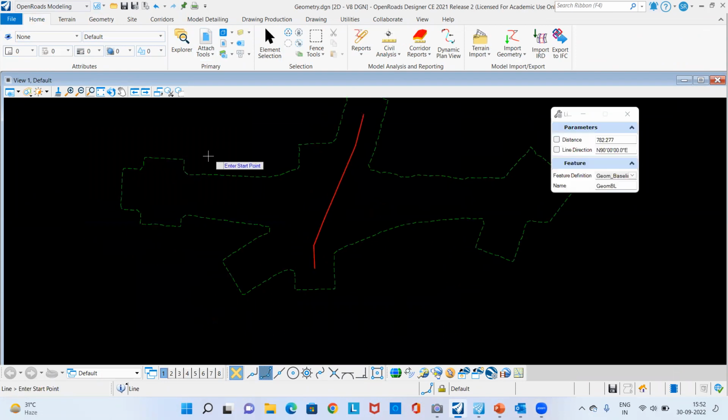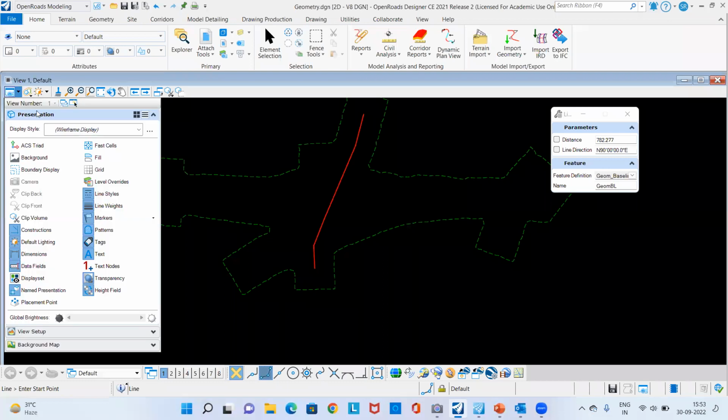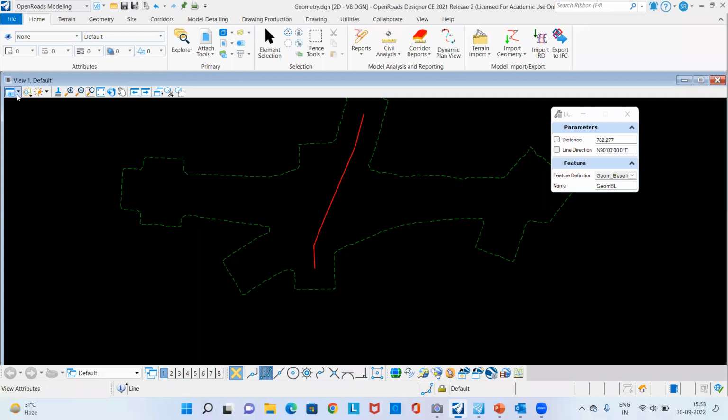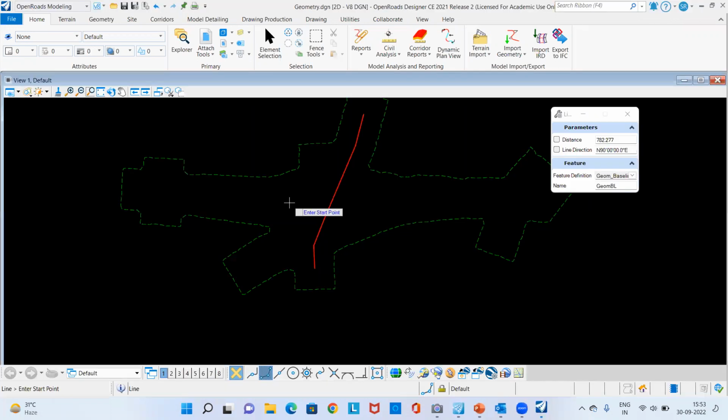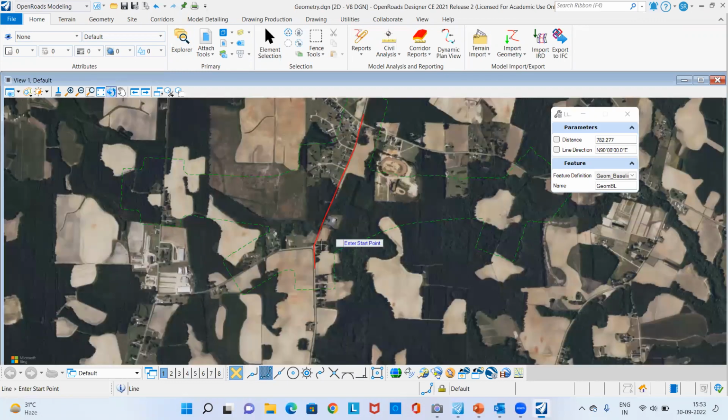Okay. Now let's check our integrated map. So the GCS is set. To view the integrated map, you must set the geographic coordinate system. Only then can you see this option here. You have three types of maps here: street map, aerial map, and hybrid map, a hybrid of both. Let's see.